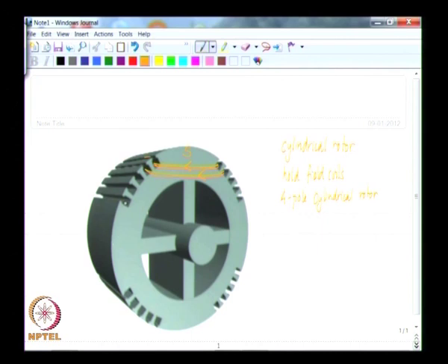So, here you have coils that are going to be laid out like this. Of course, they will come all the way from here and then go along the length of the rotor and complete the turns there, and then you have the next coil coming from here and then going this way, and you want this to generate a north pole field.